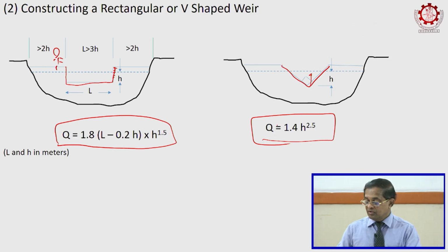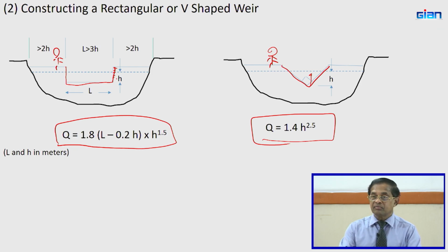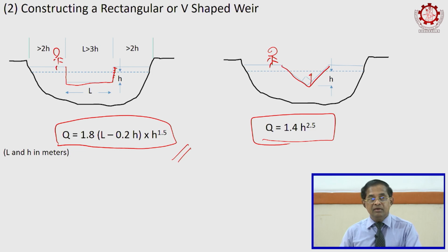So, you ask some village boy every day to take a measurement, and maybe once a week he will call you and give you the last 7 days' heights only. Once you know the height, you can do your calculation and find out the flow rate. So, the estimation will be checked further. What the hydrologist gave as the flow data, we will have a second check, because we are spending a lot of money for the project, and if the flow data somehow is wrong, then our entire expectation of energy generation will be affected. Therefore, it is always better to double check.